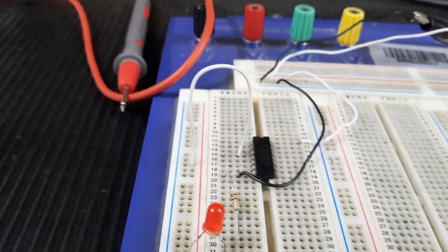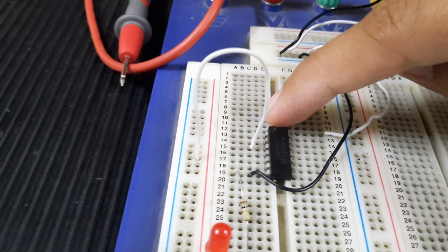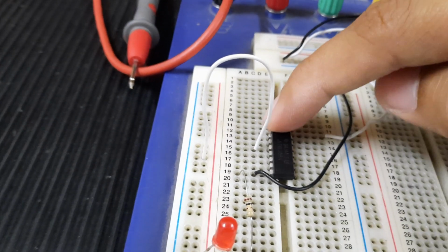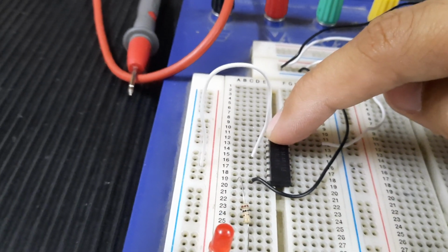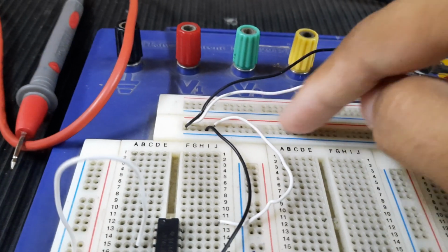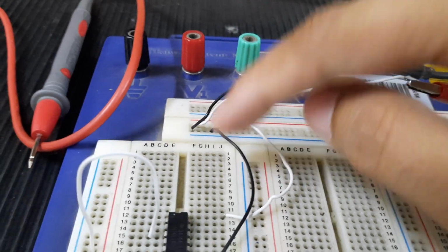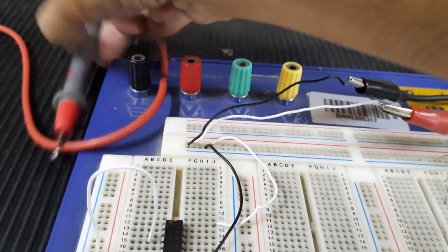Okay, so this circuit. Now one thing is remaining, that is input. For example, you want to check it on 1 1. So what you will do is give both the inputs 5 volts, obviously by taking the 5 volts from this whole row, because this upper row, the red one, is on 5 volts and the lower row, the blue one, is on 0 volts.